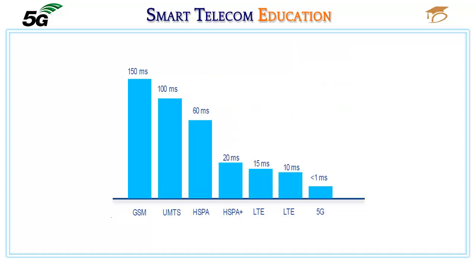The latency of LTE is superior to that of 3G, but still inferior to what can be achieved with the wired internet. LTE has a 10 millisecond frame and 1 millisecond TTI, which are hard limits for latency. The new 5G subframe will be at sub-millisecond level, to set a base for short latency.